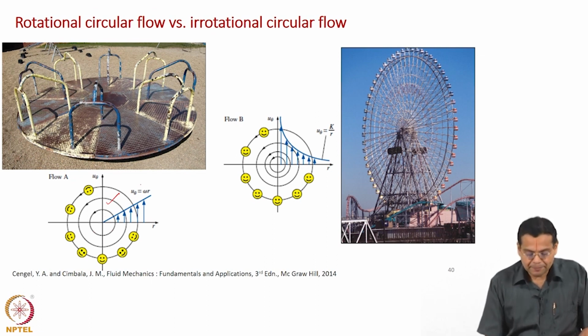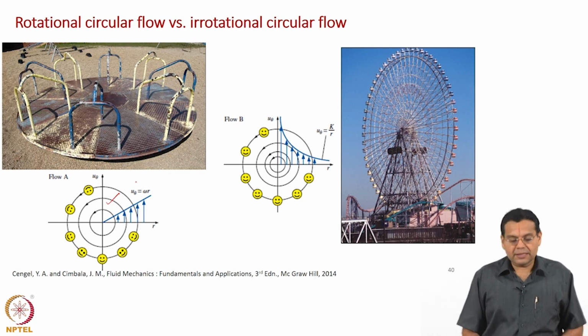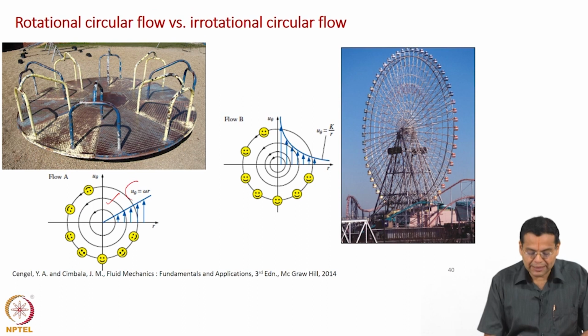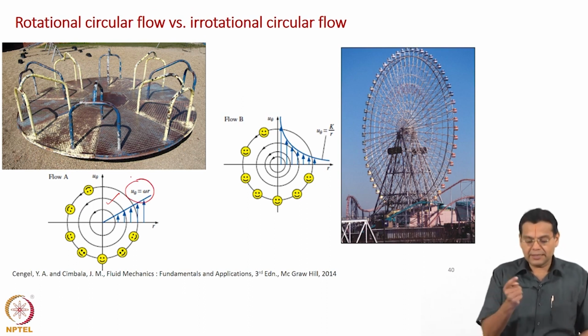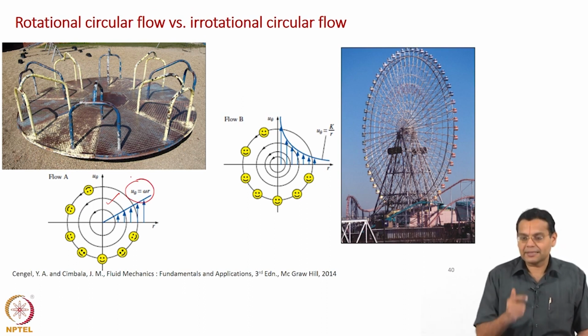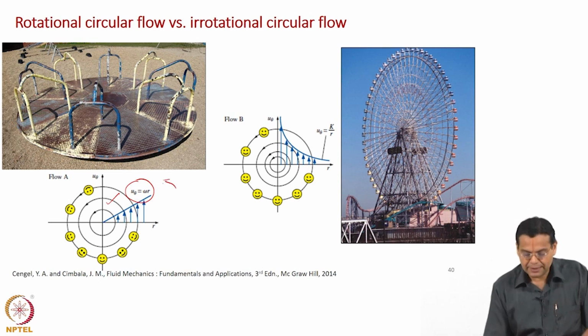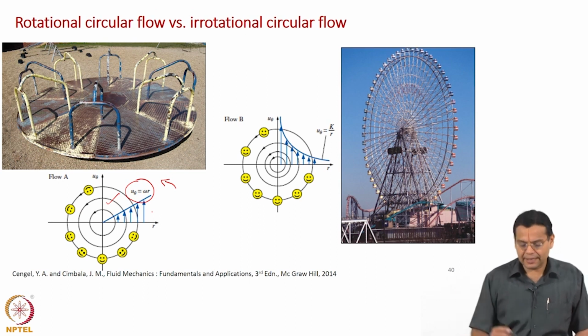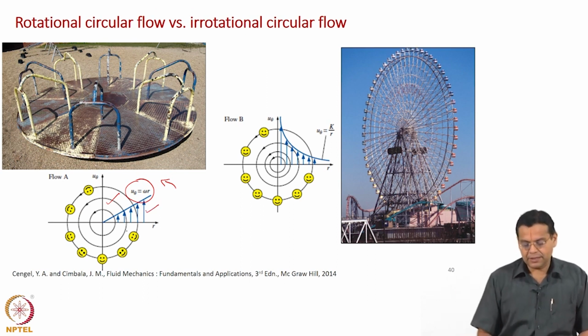Because we are discussing circular rotational flow, we can't avoid polar coordinates, though we avoid them as much as possible. So, what is shown here is u theta. What is u theta? Velocity in the tangential direction, the theta direction, and that varies linearly with r, the radial direction, and that is what is shown here. This is circular flow showing streamlines and the velocity vectors.